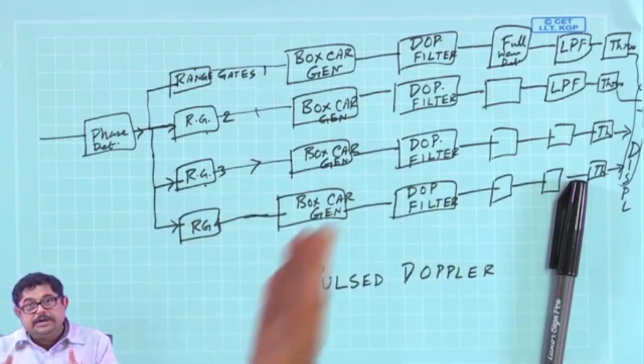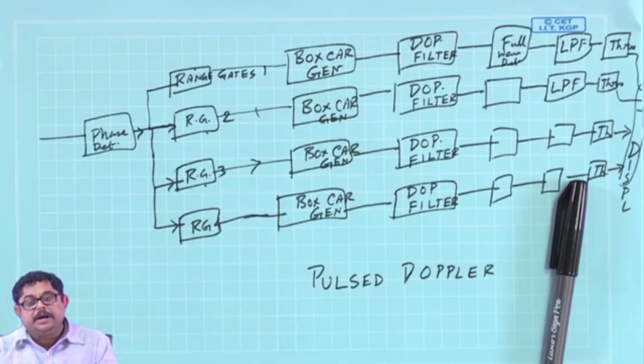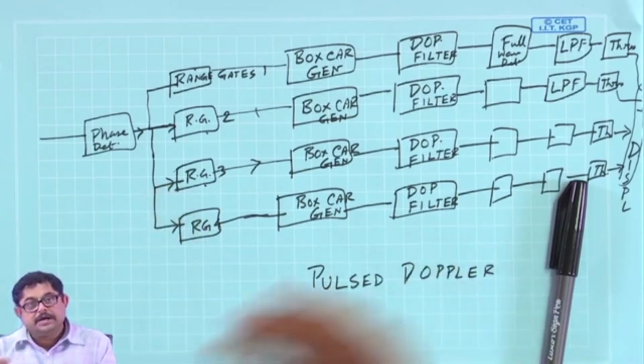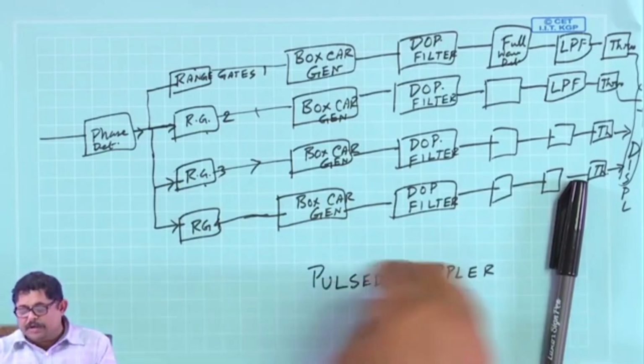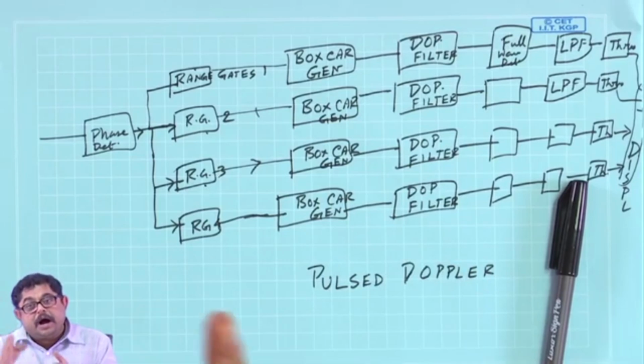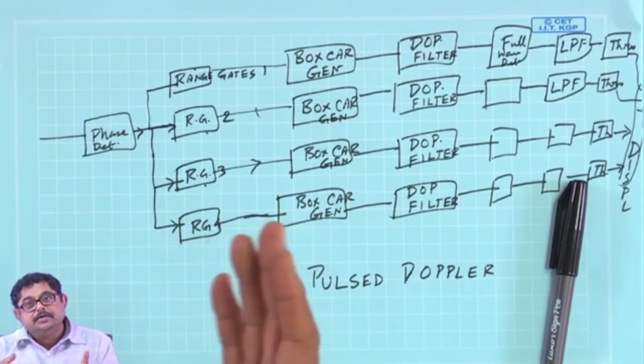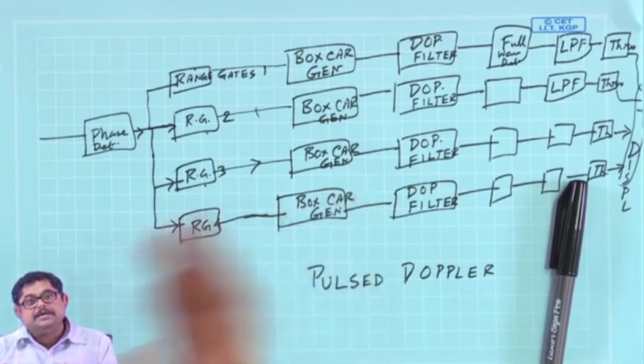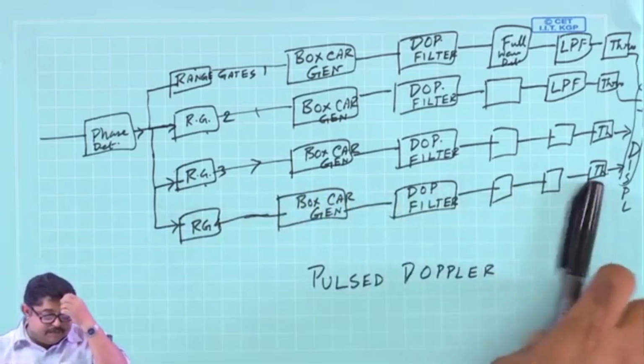Now, what is the intention of the radars, whether it is a search radar or a track radar. We have seen how to extract range and how to extract the velocity through Doppler, but we have not seen how to find out the angular position of the target. Actually, that will be done by the tracking radars. So, that will be entered from the next class.